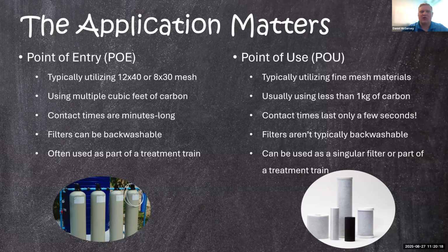So these sorts of applications are somewhat similar to a large-scale filter you might see at a big water plant, just scaled down. They're still using larger beds of carbon, with cubic feet of carbon, and having that typical 10 minutes of contact time.